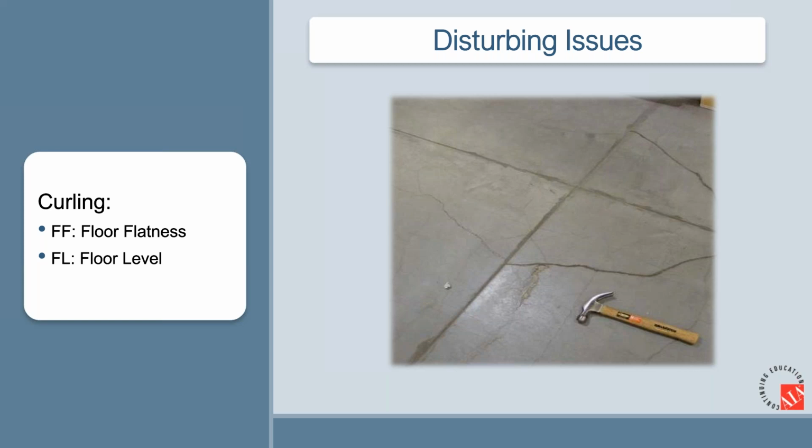Then, as forklift traffic in this warehouse drove over it, eventually the load and the stresses caused it to snap, dropping back into place, resulting in this circular crack or radial crack around the joint. This can be prevented or fully eliminated if you ensure to cure the vertical surfaces of the joint wall the same way you cure the top of the slab and the same way you cure the edges of the slab.